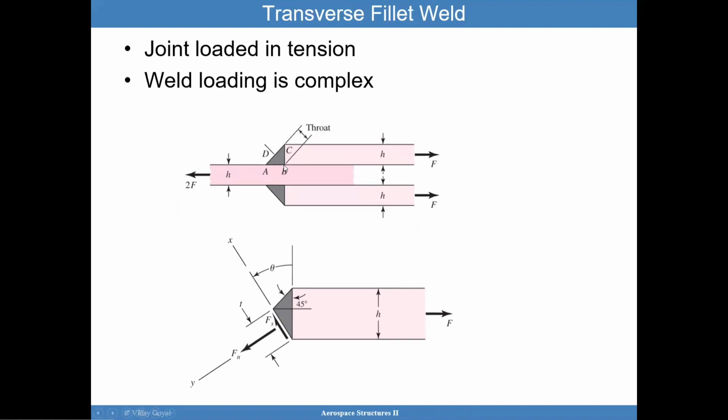Recall, from here to here, that's your miter weld. And so I'm going to draw this carefully here. I've not drawn the whole triangle, but I cut through at some angle to study the shear stresses within this weld. I have a normal stress or normal force to that plane. So it's an arbitrary cut right through the weld. I'm only showing the top here. And an angle theta here, and presume this is 45 degrees. This is your T there that we discussed earlier, okay?